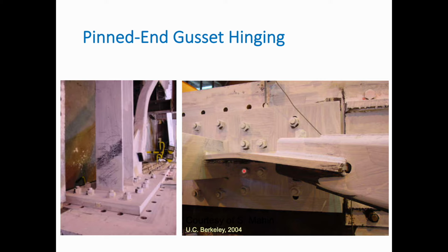In fact, you will get some sort of bending and deformation even if you have a thick gusset plate. However, that is not failing, so the bracing has done its job by buckling, so it has already moved in a ductile manner.